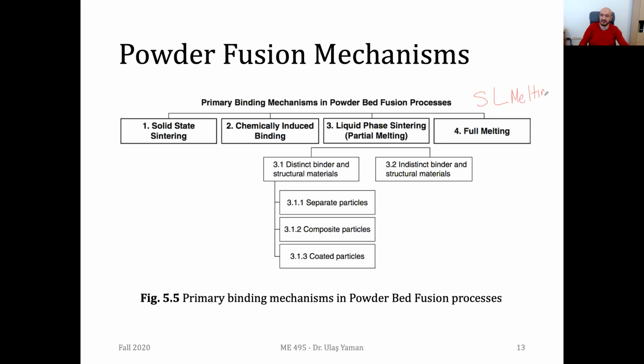There are some companies using this process, but the fundamentals are the same. The only difference is that they are using powerful lasers, and they increase the temperature of the powder to its melting point, not just below the glass transition temperature, but above the melting point. In the other ones, the temperature is usually a bit below the glass transition temperature. So I can say that we have this infinitesimal value here once again, but this time the temperature should be higher than the melting point temperature.